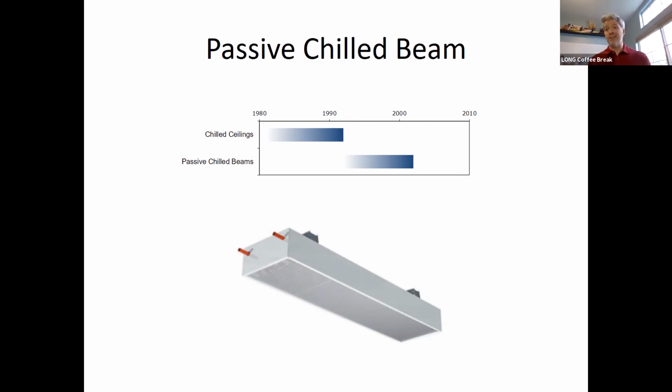However, if you go to something like a Runtal panel that's mounted on the wall, especially low, set up directly underneath maybe a drafty cold window, you get a lot of convective. And you'll see those numbers from radiant versus convective drop drastically down into the 40s or that 35% number. So even though you may be specifying a radiant panel, depending how you put it, you're not getting a lot of radiant out of it. A lot of the heat coming out of it is going to be convective anyways, which could be beneficial depending on how you're trying to use that device itself. So hopefully that's answered some of the questions.